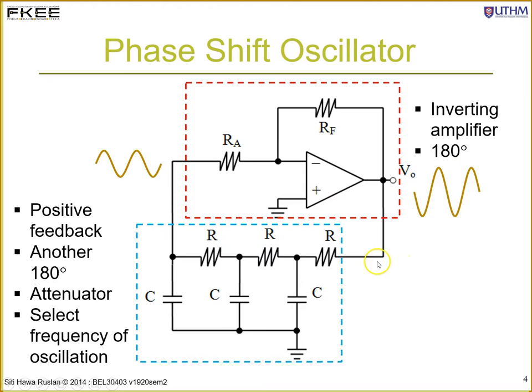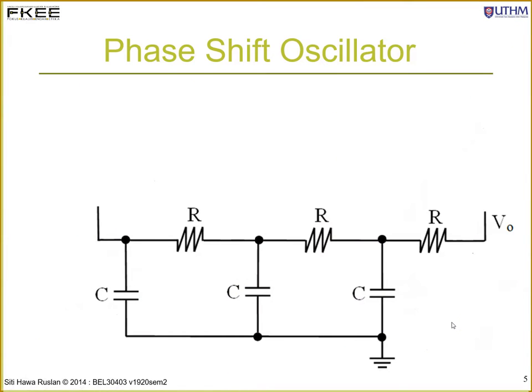Your output signal will be fed to this feedback network, and the signal will be lowered, okay, in terms of the amplitude, and it will be amplified again. So there is a closed loop, and this must fulfill the Barkhausen criteria of 360-degree phase shift around the loop, and beta, this is your beta, multiplied with the gain must equal 1. So this is what we'll analyze. Okay, and we just look at the feedback network.